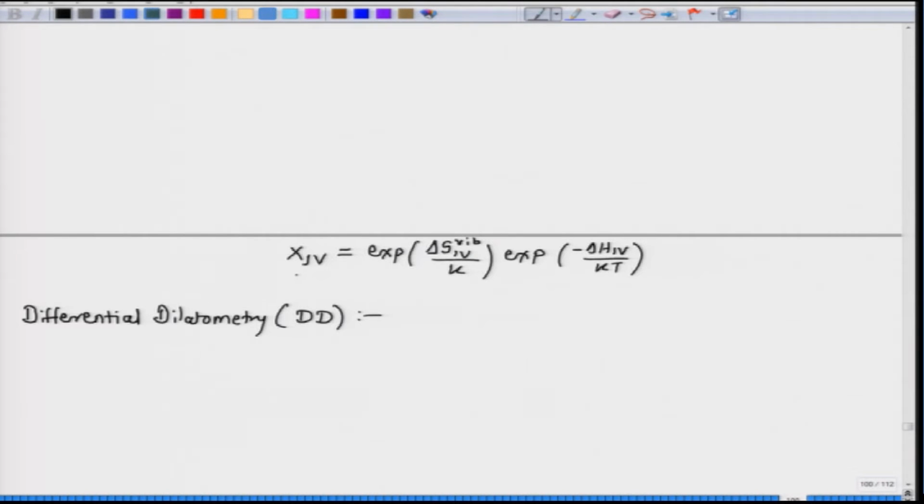So as the temperature increases, to maintain the equilibrium, extra vacancies are formed, and so extra lattice sites are added to the crystal structure. This will give rise to the second contribution to the net volume change caused upon heating. If we can measure this volume change and the individual contributions, we can relate them to the vacancy concentration, and that is the principle here.